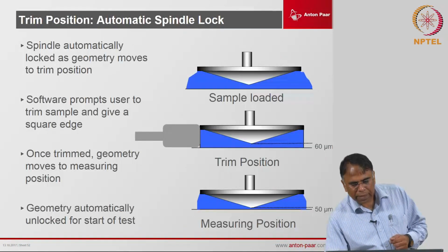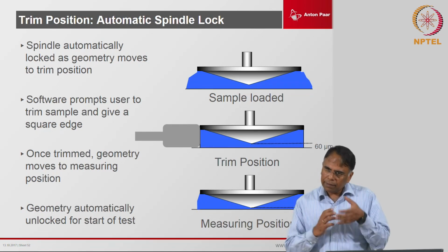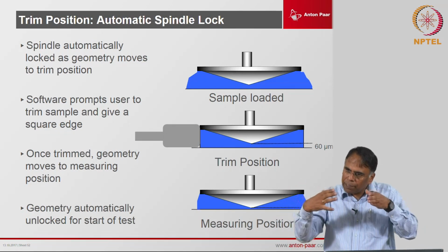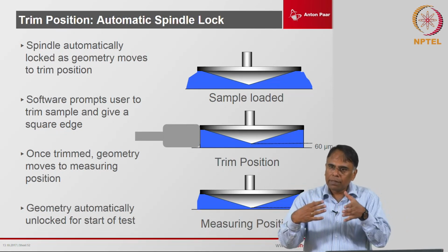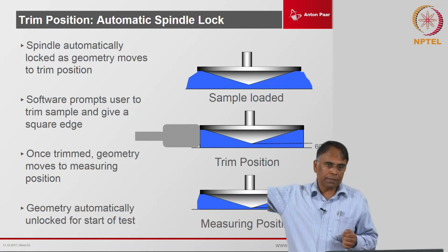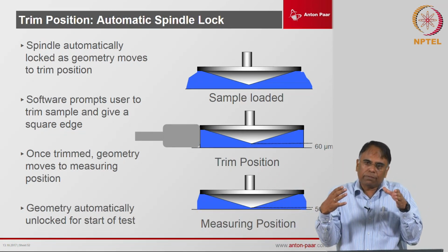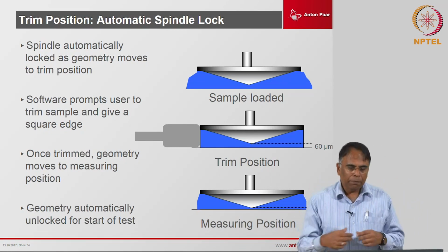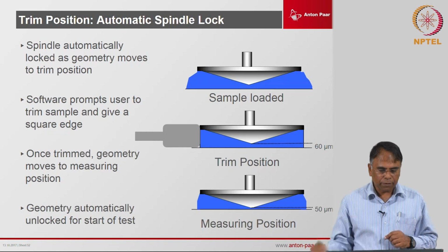Of course, you will see that many times, specifically when you do a steady shear experiment, because of the centrifugal forces the sample can actually get contracted inside. That is the reason this extra bulge will help you out. For example, if you have an ink sample and you want to measure at a shear rate of 1000 second inverse, it is very important to have this bulge, so that at this high shear rate of 1000, the ink is going to move inside a little bit, but it will still maintain the full gap condition even at that high shear rate.